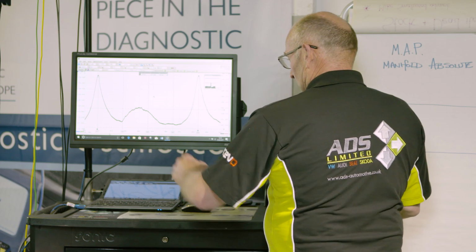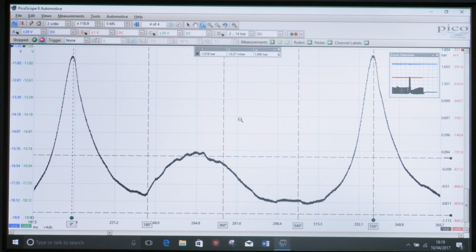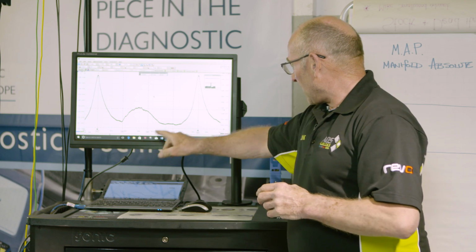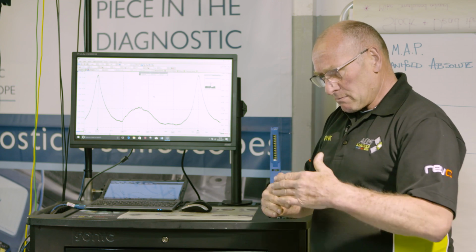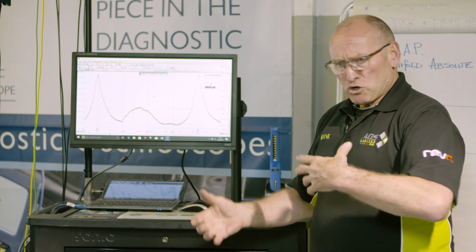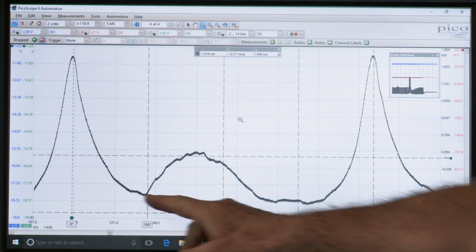So, intake stroke, clean air. The piston now is definitely on the way down here, drawing in the fresh air charge, which, assuming there isn't a blockage. Now, what would happen if the inlet valve didn't open, or there was a severe restriction on the intake system? This pressure is going to go even lower. You're going to get an unduly high intake pressure differential, and it's going to pull this pressure much lower than the 300 millibar we anticipate as being a good figure.